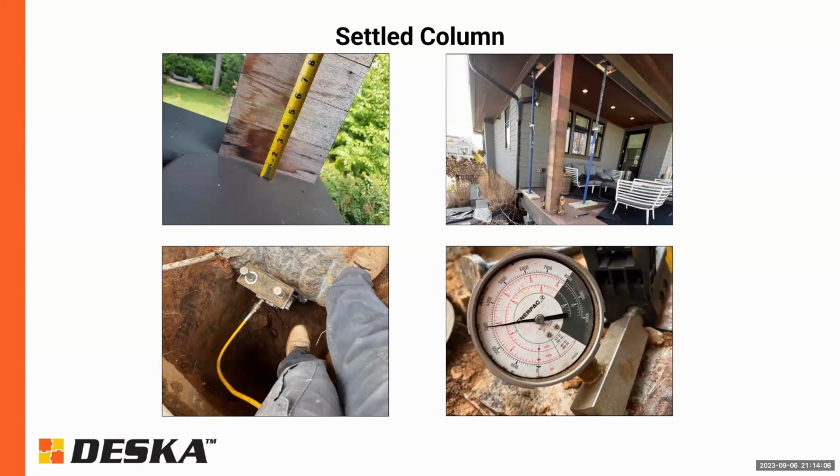In this particular case, temporary bracing had to be installed, which was a little bit tricky because you have a structure below it that is also being braced by the same column. But essentially the column footing needed to be underpinned with a helical pier, and that helical pier needed to go about 10 feet minimum to get down below that disturbed soil until it met its appropriate capacity to support that load above.